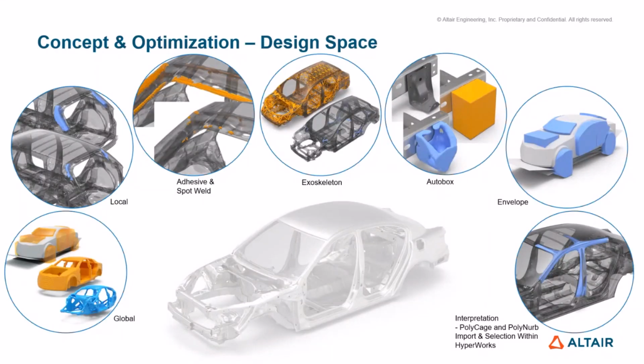Okay, I wanted to start by just giving a really quick recap of all of the concept modeling and optimization capabilities available today. So related to design space, you have the global body in white or subsystem design space setup, local for doing structural adhesives, structural baffles, structural inserts. It can also be used for castings. So this is where you've got a design space that is very localized. You're kind of space constrained.